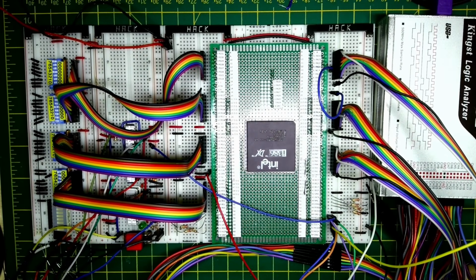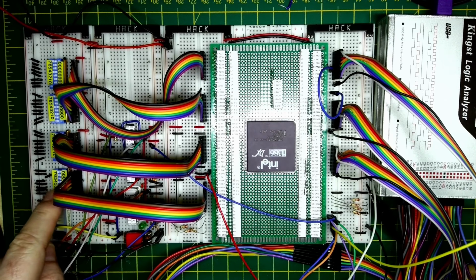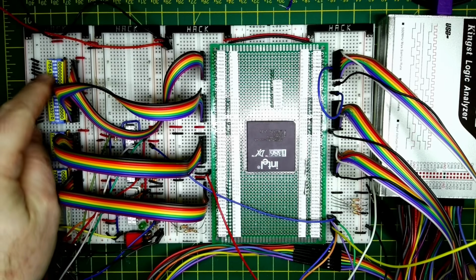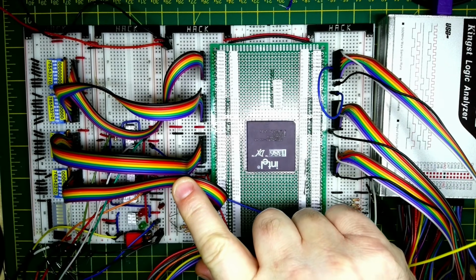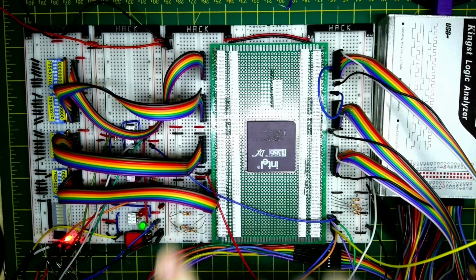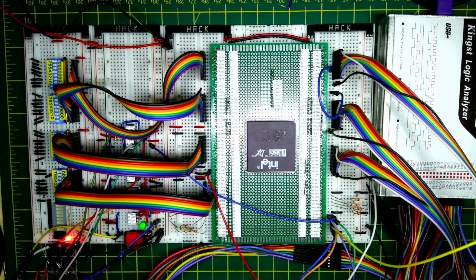Okay, so let's turn it on, and you'll see that the red light down here will come on initially to show that the processor's in reset, and the green light will then show when the processor is running. And we've also got our 90909090 all set on here. So I'm just going to set the logic analyzer to be waiting for the power to come on. Turn the power on, just move the cable so you can see the lights. So you see that the red light came on initially, that's when we're doing the power on reset, and then green means the processor was running.